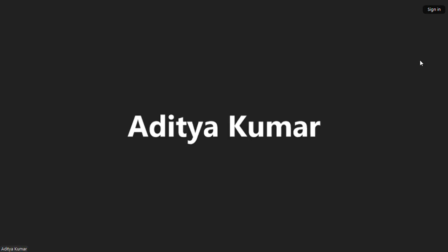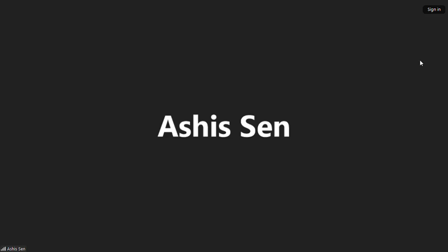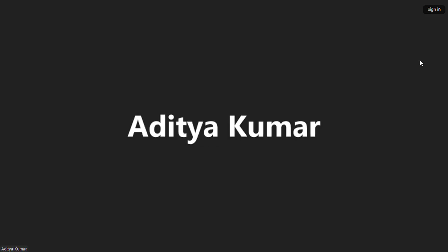There are some applications where you do not want to keep the reference junction fixed. What you do is that you use what is called a differential thermocouple. There it is the temperature difference delta T which is important, not the absolute value of the reference temperature. So I will talk about that in the next class. Understood, sir. Thank you so much.